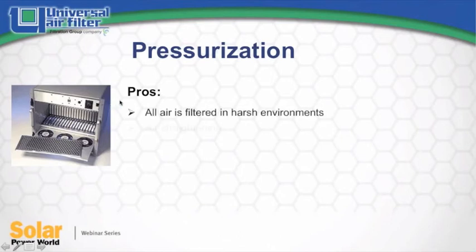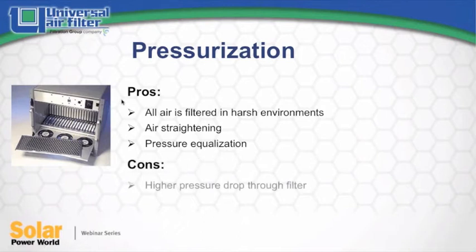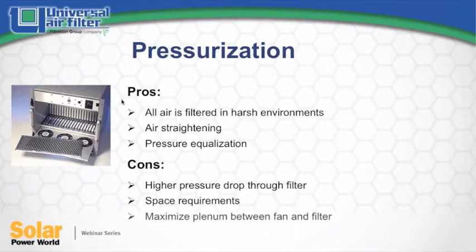Pros and cons of pressurized enclosures with fans pushing cooling air in. The upside is all moving air is fully dust-free, and the filter is utilized to distribute the airflow in a laminar pattern. Some of the downsides are you need to add room generally to accommodate a space between the fans and the filter to take full advantage of the complete filter surface area.